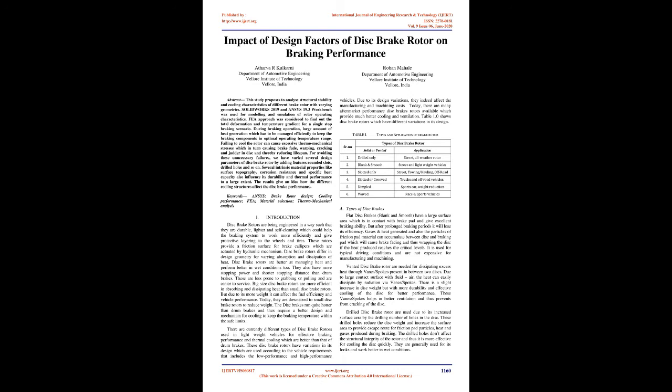FEA approach was considered to find out the total deformation and temperature gradient for a single stop braking scenario. During braking operation, a large amount of heat is generated, which has to be managed efficiently to keep the braking components in optimal operating temperature range. Failing to cool the rotor can cause excessive thermo-mechanical stresses, which in turn cause brake fade, warping, cracking, and judder in the disc, thereby reducing lifespan.